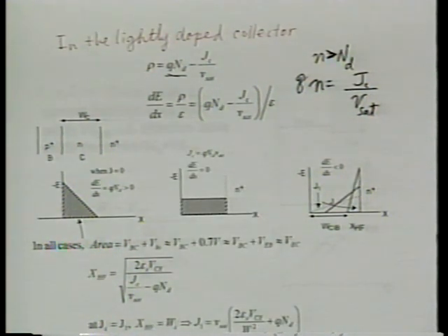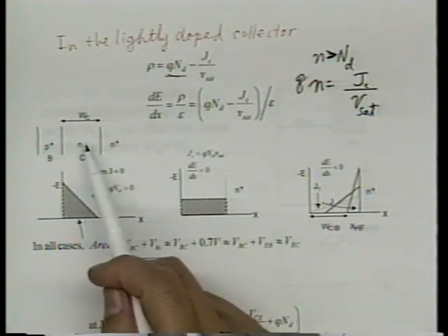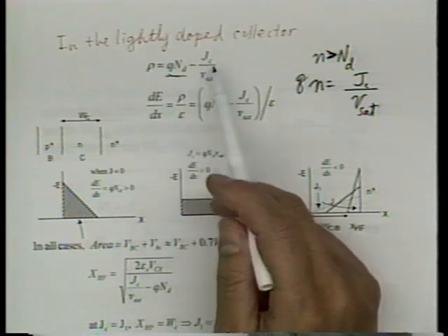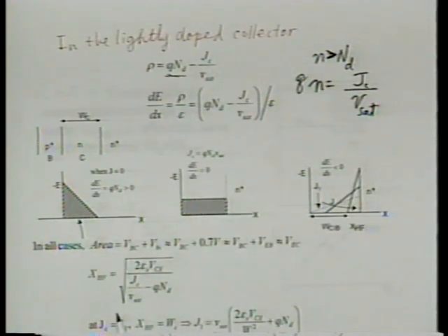So what's new is our lightly doped N region is no longer neutral. That's how it has to happen. It's no longer neutral. Specifically, it will be negatively charged, let's remember, all right? Because we have now more electrons than we have donor atoms. So this will be negatively charged. Now, before I show you more math, I want to show you some drawings.